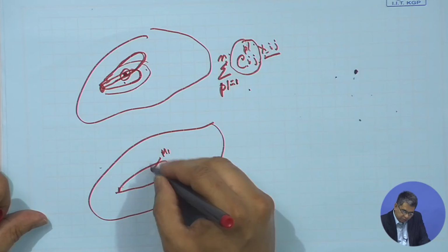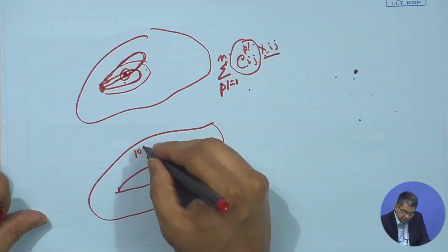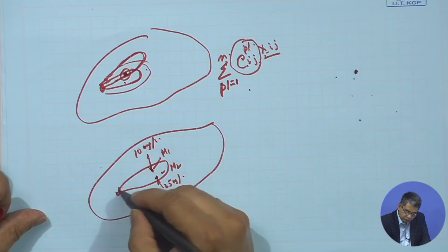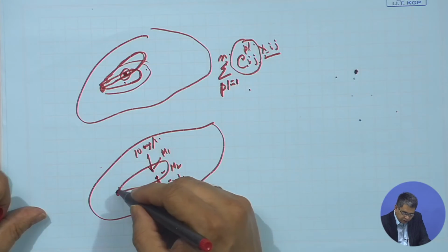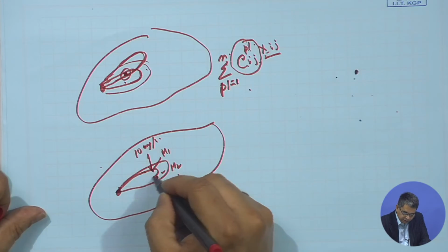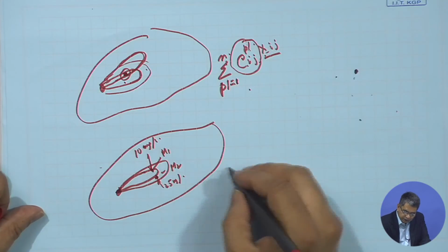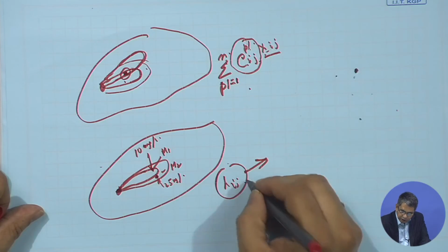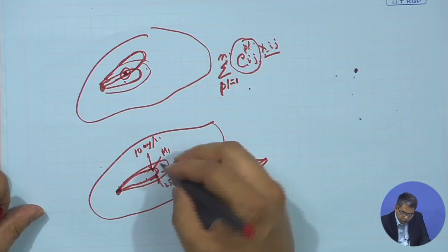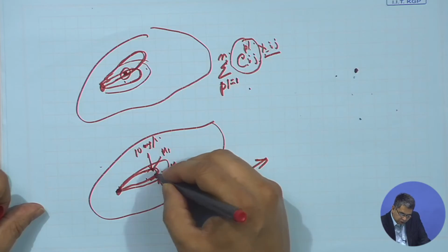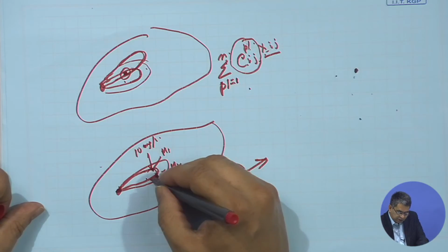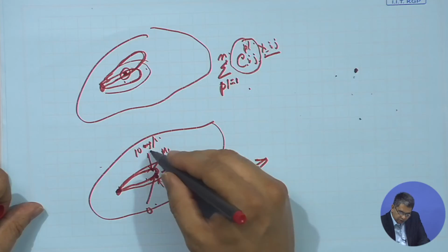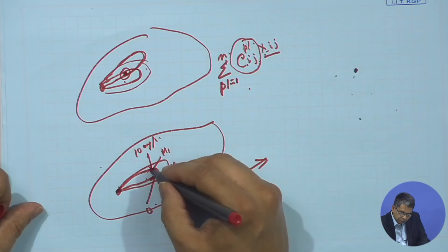And for this particular plume, this has got some value, maybe 10 milligrams per liter or something like this, and this may be 25 milligrams per liter. Then I change my source randomly, and maybe it is smaller, so it might look something like this also. At the same time, not only the source, but I might change the hydraulic head distribution Hij, because that is also uncertain. I can randomly generate some of these Hij values, and that gives me this plume. And for this case, it is almost 0 for this one, and of course 25 for this value, and as you can see, it is out of the boundary. For the second plume, it is equal to 0. Okay. For this one, maybe 10, and maybe almost 10 or 11 for this one.